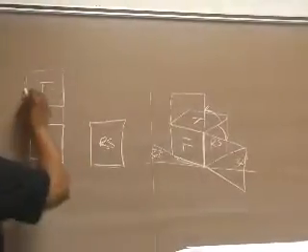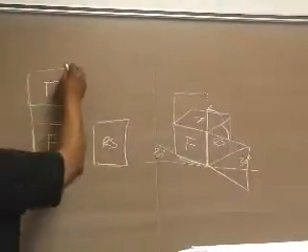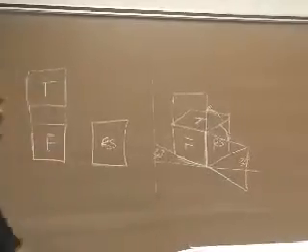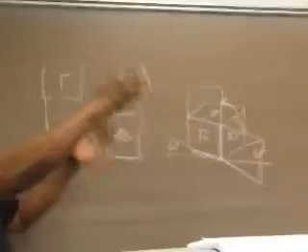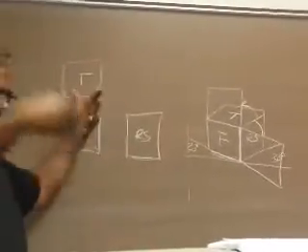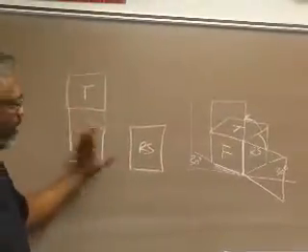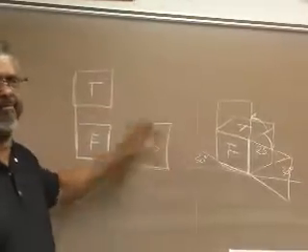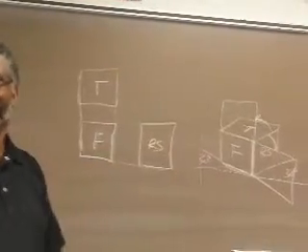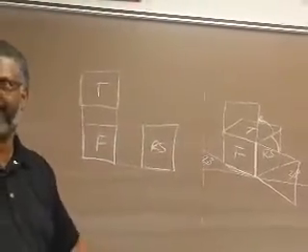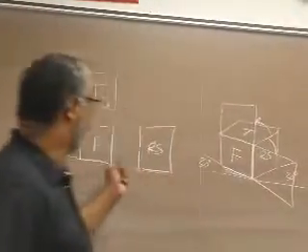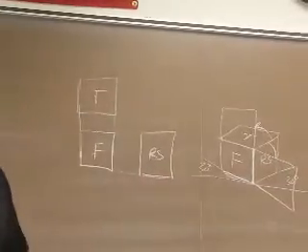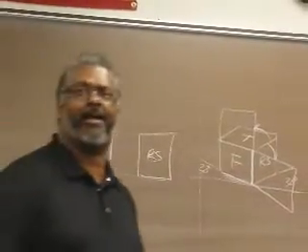That's why these have to stay in alignment with each other. Just like you open up a cardboard box, when you open it up, they hinge together. They stay in that formation. They're not offset or anything like that. Not front, right side. That's very basic, even in orthographic drawing. If you don't get that, you're going to be having trouble as a drafter.